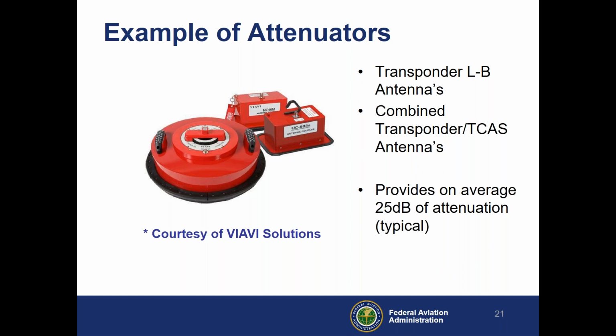I believe they have a minus, somebody can correct me if I'm wrong, but about a minus 84 dBm of sensitivity. So they're very sensitive. So take all precautions you can. They're more sensitive than the airborne equipment. That's correct. I think the airborne equipment's minus 74. All right, thanks, Kerry.